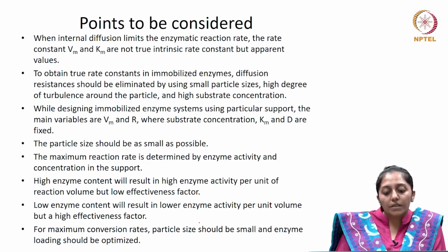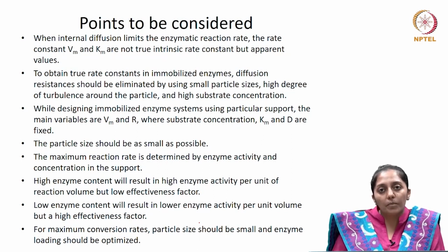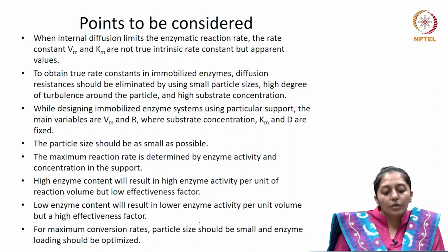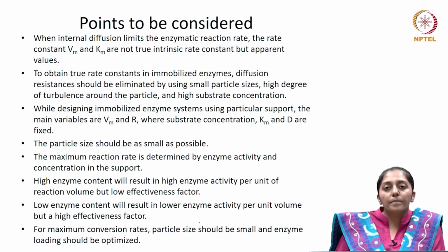Now, the Km, which is the affinity of the enzyme towards the substrate, and D stands for the diffusivity of the substrates, these we assume are fixed, the given values, because the substrate is given. So, the particle size is what can be manipulated or designed, and the second is the enzyme concentration which is being immobilized in the system.